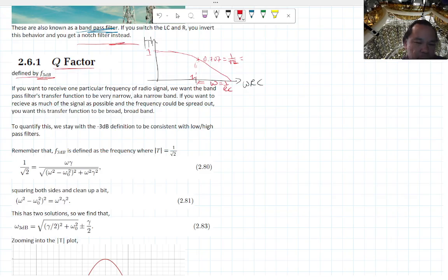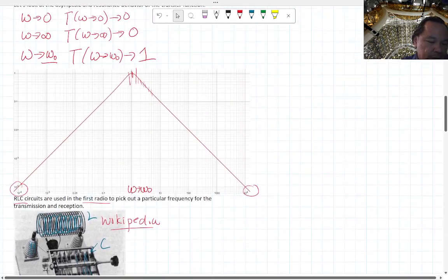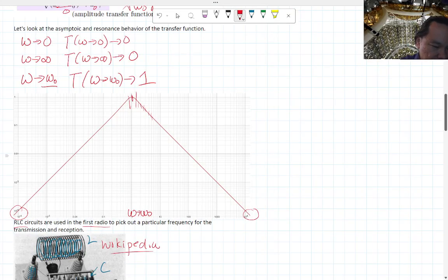This is known as the F3 dB point because if you convert this to the attenuation version of it, this is exactly equal to -3. So you have some transfer of plotting to go between those two concepts, but they're always called the F3 dB point. It's not called the 0.707 point, but they are actually the same thing. What we're going to do is the same thing for our RLC circuit, where we're going to go down to the F3 dB point.